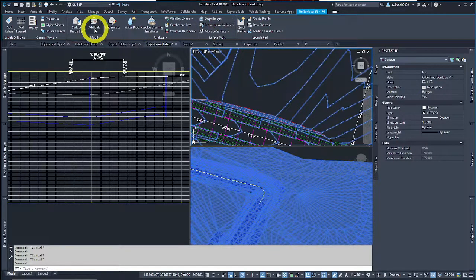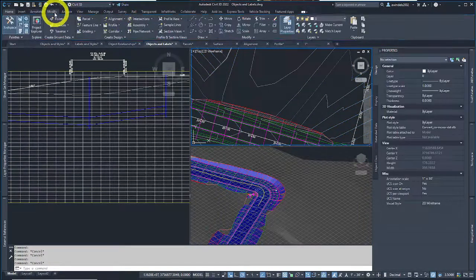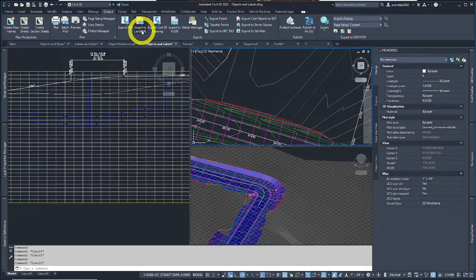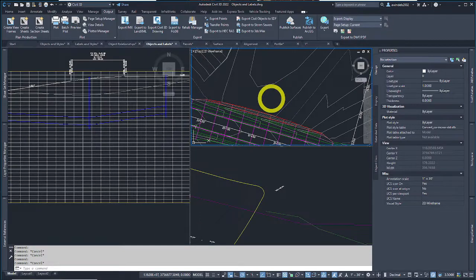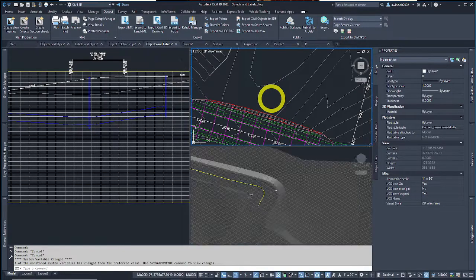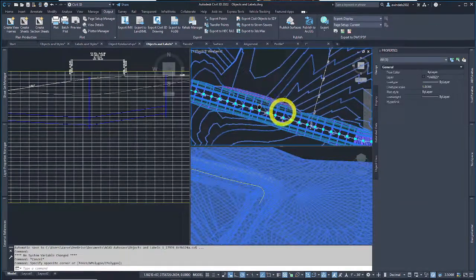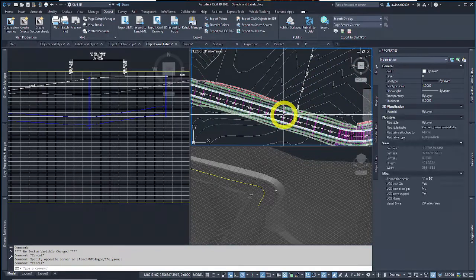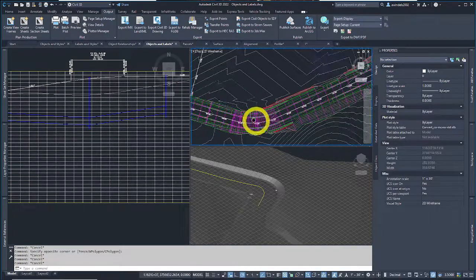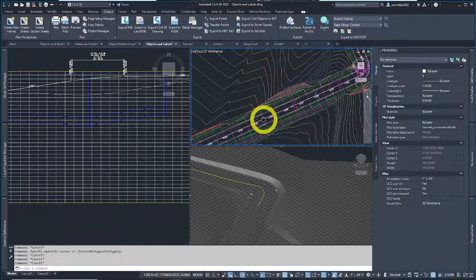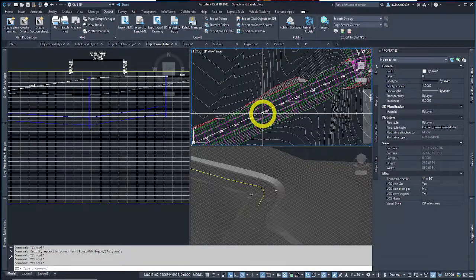We can extract data. We can also go to output and export LandXMLs of various things and different types of data to go to an earth mover, and some of those data formats like DEM and LandXML get literally input into the GPS of a bulldozer or scraper, and it'll tell them how close to the design quantity they are as they grade this new terrain out. That's a big thing nowadays.